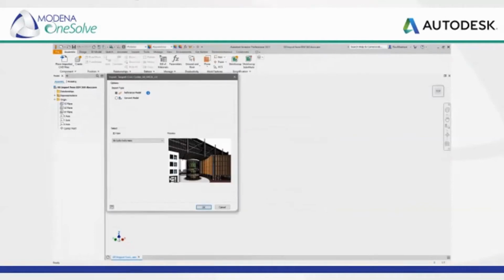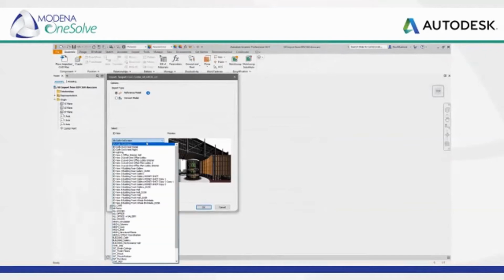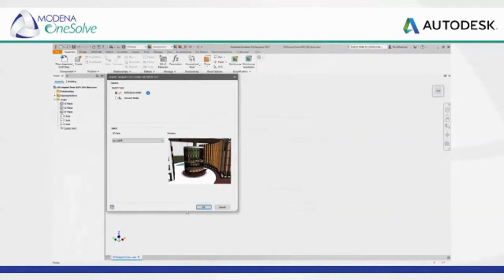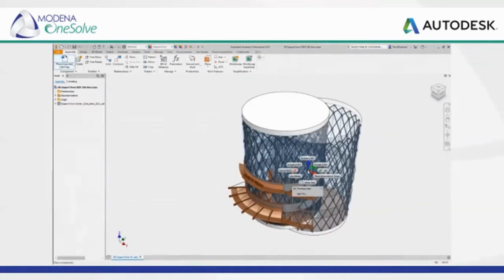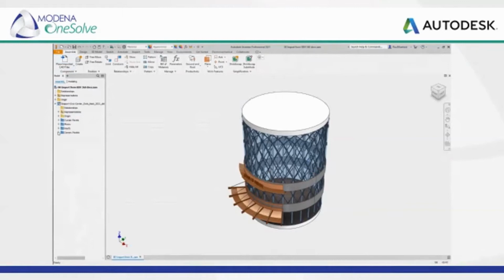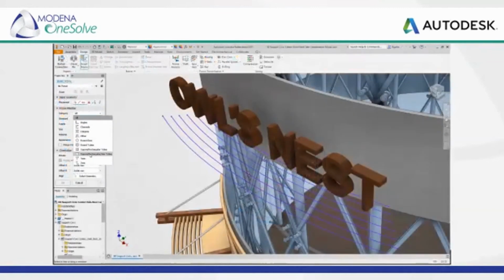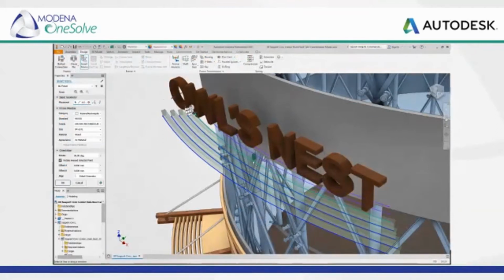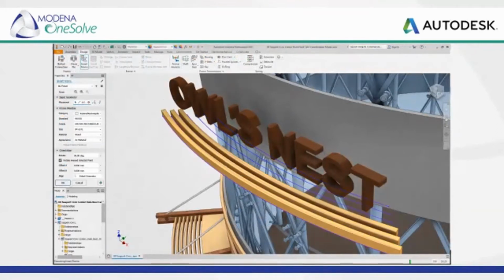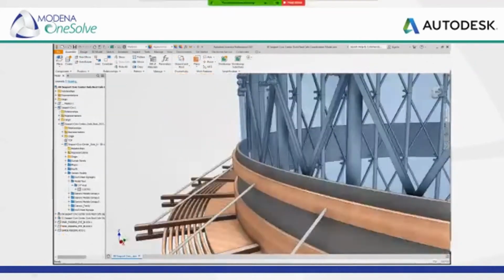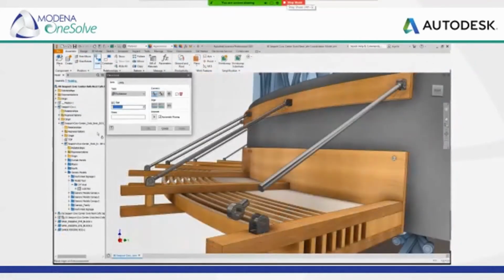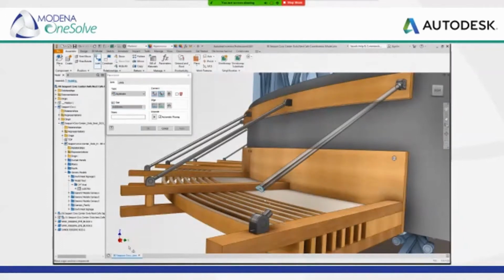On referencing a REVIT file, custom views from the REVIT project can be selected in Inventor, allowing it to filter the BIM to just the information you need. In the Inventor browser, the REVIT model is organized by category, allowing you to further examine the structure of the model and filter the BIM to your requirements. Once placed into your Inventor assembly, the REVIT project can be used as a reference model to help guide your design. Working with the native REVIT project helps you locate your design using shared coordinates, size your design appropriately, and coordinate your design against the integrated BIM.